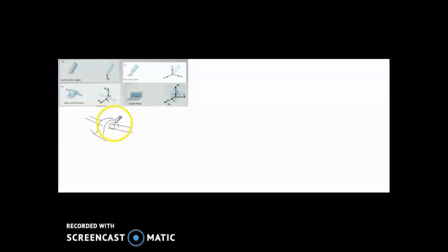It will have a force in the Fx and Fy directions, but no force here, because it is free to translate here, back and forward, so there is no tendency for a force to be created. And for the moment also, it is only created in the Fy and Fx positions. There is no moment here because the shaft is also free to rotate.